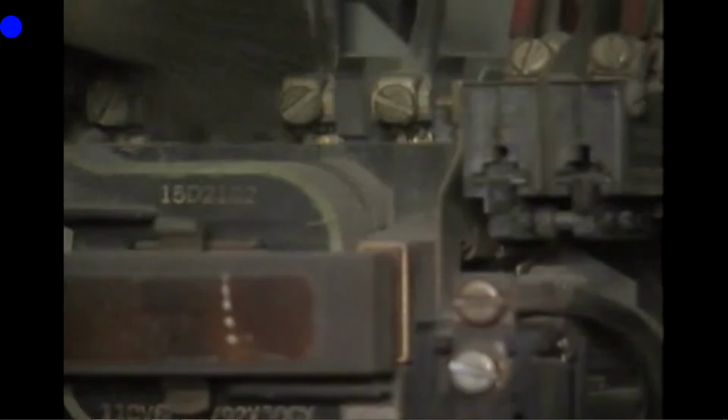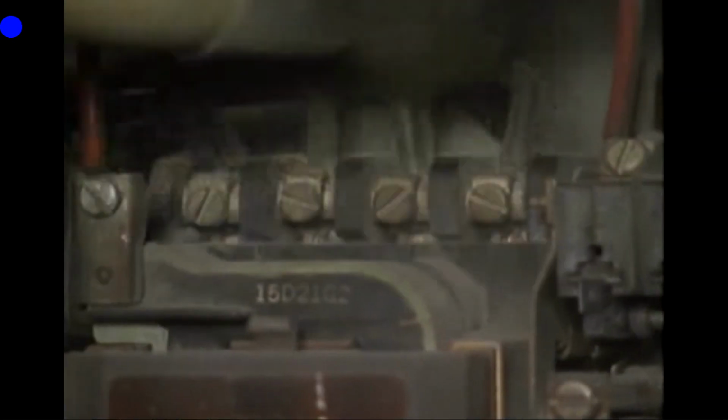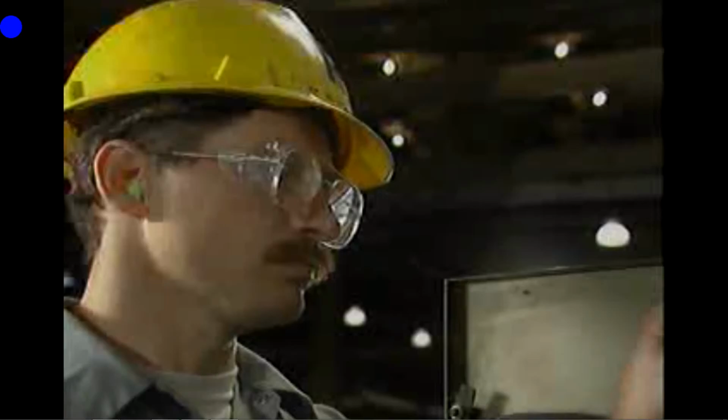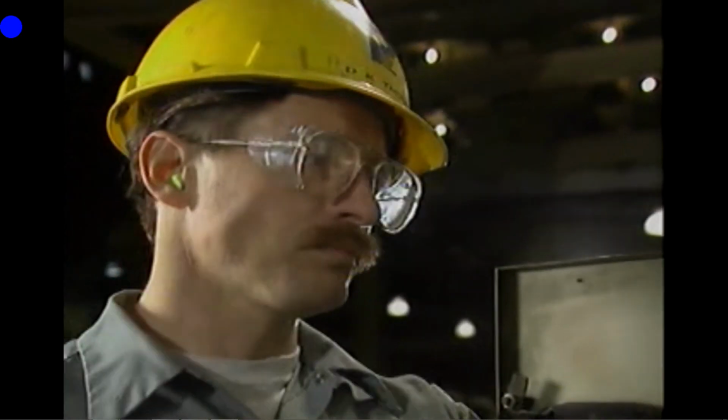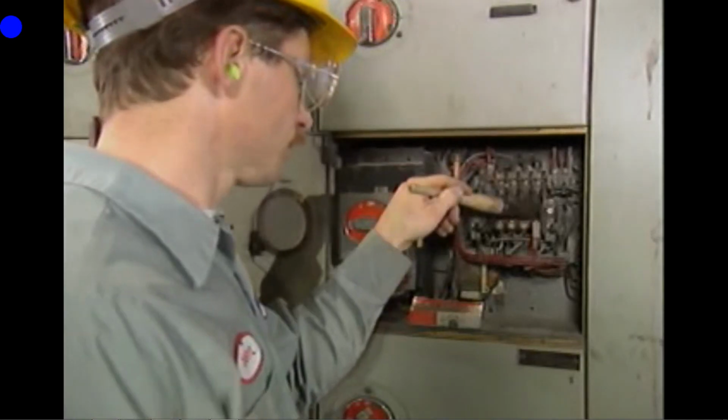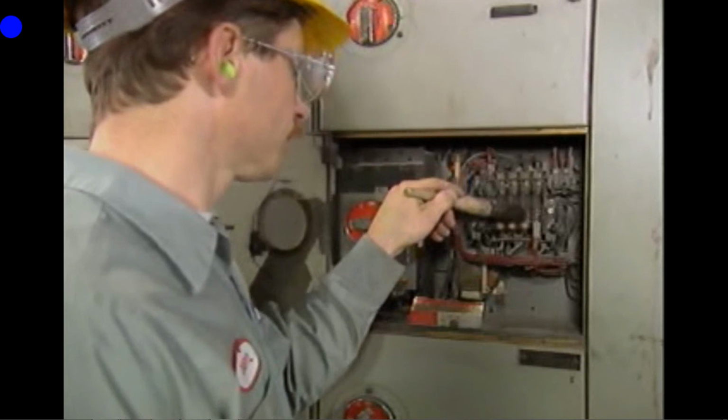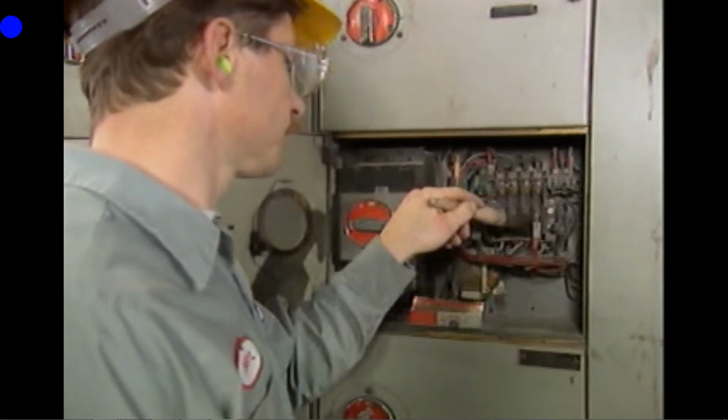Dust, dirt, or other contamination inside a controller's circuitry can also cause shorts or grounds. And if dirt gets between contacts, it can prevent the contacts from closing properly, which can result in an incomplete circuit. Another reason for cleaning a controller's contacts is that contamination on contacts can cause an increase in resistance. Increased resistance, in turn, can result in the generation of excessive heat, which can damage contacts and burn insulation.